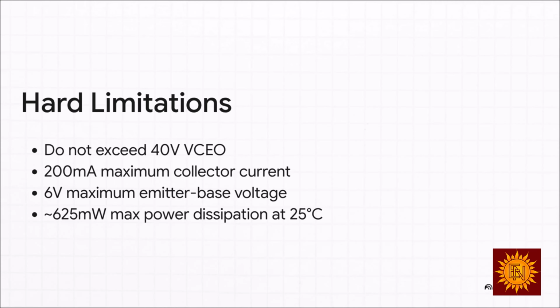If you try to continuously run 200 milliamps through it, you're going to push right up against its 625 milliwatt power dissipation limit. And no, before you ask, strapping a tiny little heatsink to a plastic TO-92 package will absolutely not save it if you push it beyond those thermal limits.